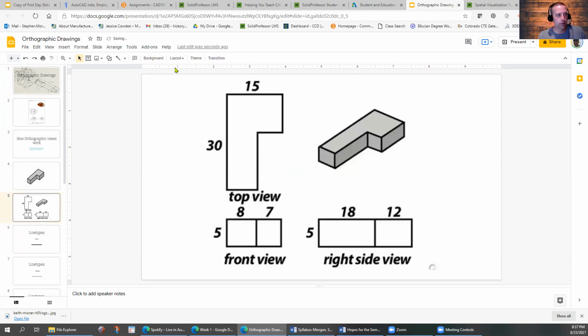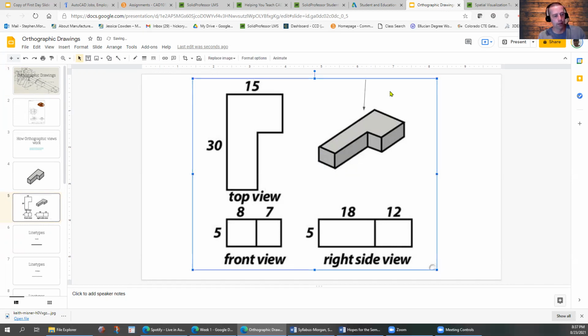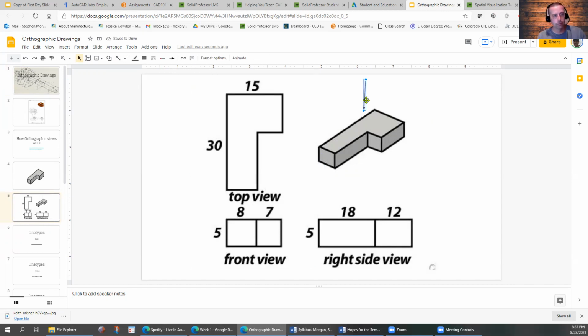The top view is just the way it sounds. It's going to be looking basically straight down at this block from up there. And you have to recreate it as if you're floating above it. And then obviously the other side is right there. So as if you're a little miniature person standing looking directly at the side. So if you can imagine standing here, this is exactly what you'd see. So it gets tricky. So even with an object like this, this might not be what you assume you're going to be seeing looking this way, but that's what it is. It's 2 little squares and there's no depth to it.